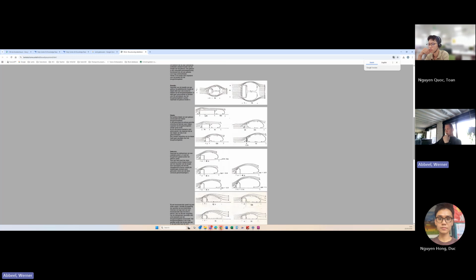If you have a building like this, if the wind comes from one direction, it will go up. It will here go against the wall, turn. But if it here goes up, there will be some turbulences here on the edges. So that's how it's calculated. On the edges, you need more ballast than in the middle of the roof, because here will be some turbulences. It will make some sucking on the modules, create a lift. Therefore you need ballast, but most of the ballast is just for the gliding. So that's the theoretical part.